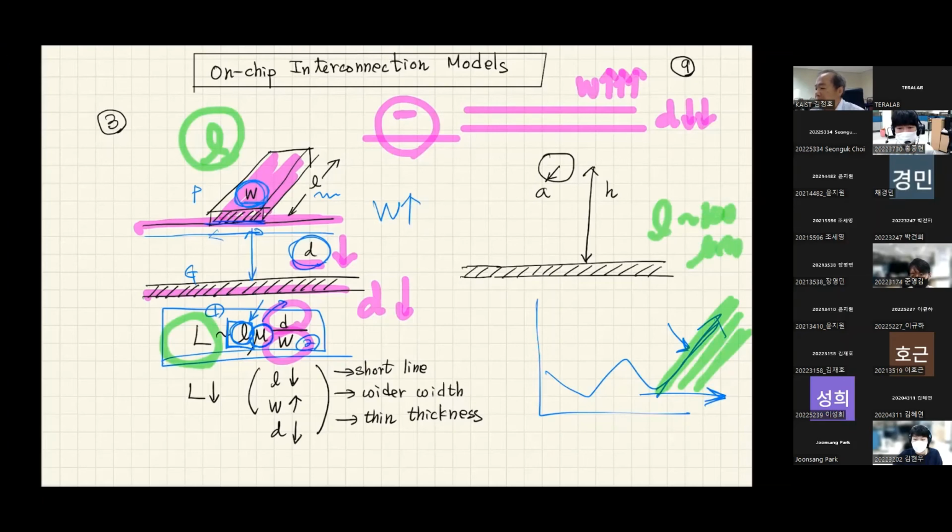And the last design parameter that will reduce the inductance is the number of interconnections. If you have more interconnections, the effective inductance will be reduced by being divided by the number n. So the number one approach to reduce the inductance is to reduce the length of interconnections. The second approach is to increase the number of interconnections. That's why I keep saying that TSV is the solution.